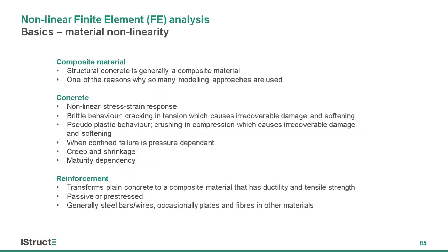So the basics. We've heard about some great stuff from Jan, but here's some basic stuff. It's a composite material, really. Structural concrete is generally a composite material, and this is possibly why there are so many different modeling approaches. Concrete has non-linear strain. We know all about that. It's brittle in cracking. Its fracture energy and its softening is often largely because of it being attached intimately with reinforcement. It has pseudoplastic behavior in crushing, and when confined, it's pressure dependent, so that you can get higher strengths.